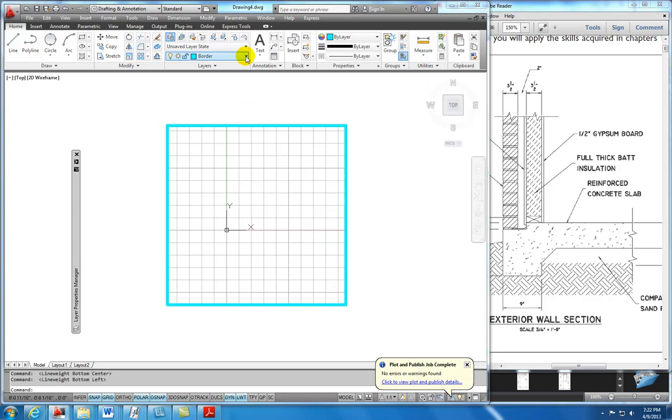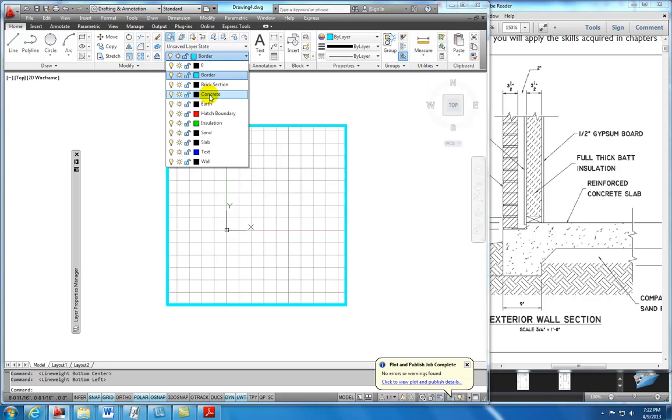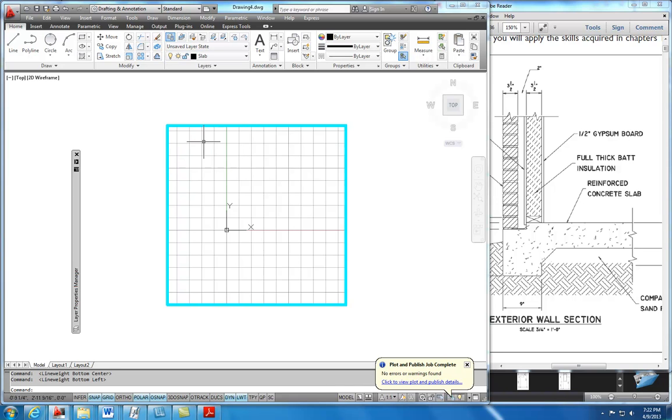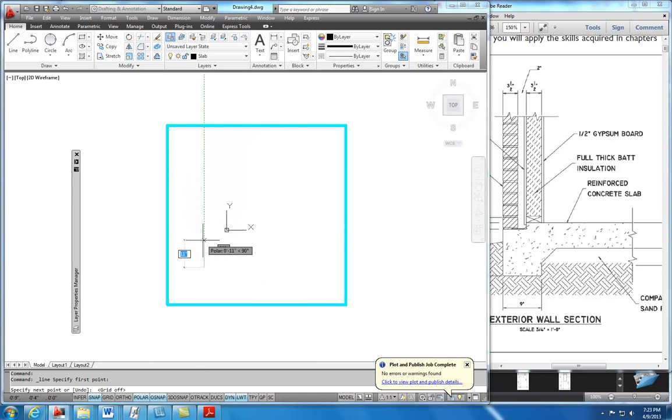We'll come over to the AutoCAD and we'll select the slab layer. It's current, so it's showing here. We'll get the line command, and then at some convenient location we'll start. You'll notice my polar button is on, so I'm tracking north. And I'm not much of a grid person. I'm actually going to turn my grid off because it kind of gets in the way. And I'm going to also turn off this UCS icon. We're not going to need it for this command. Let me hit escape and I'll type UCSICON, and I'm going to set that to off.